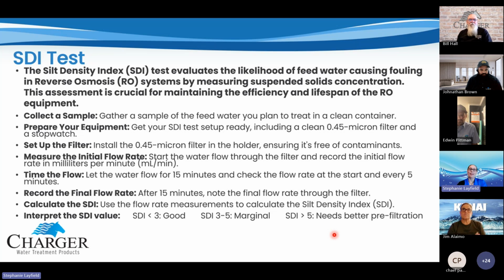Well, water's cheap. Those membranes are expensive whenever you foul them up. And this is going to be the main thing that will foul those up whenever you restrict the drain line flow.